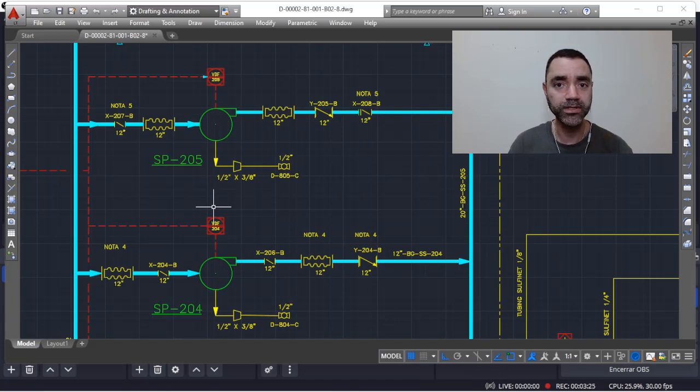What is important to understand here is that it is a saturated gas, so depending on the weather it can condense liquids, and it is a gas, it is a blower, it's not a compressor. A blower is rotating equipment where the delta P between the inlet and the outlet is much lower than in a compressor. This is a summary comparing blowers and compressors.